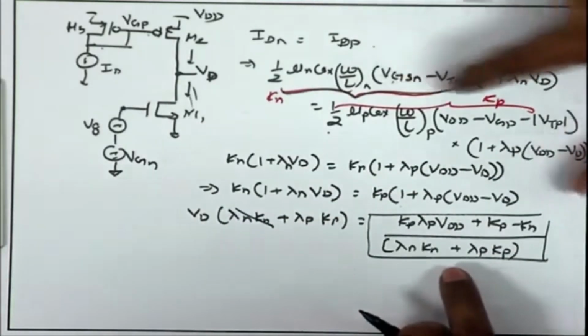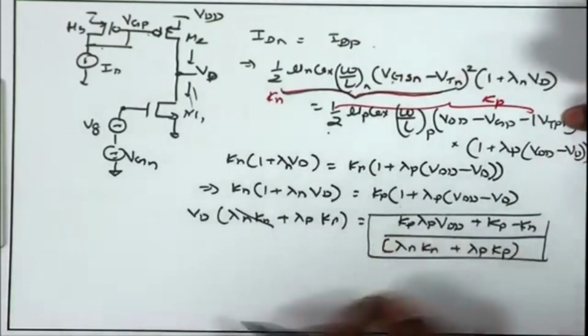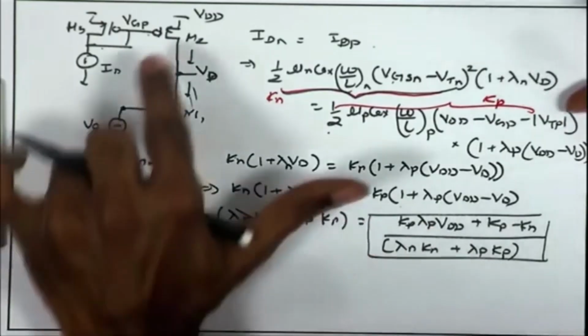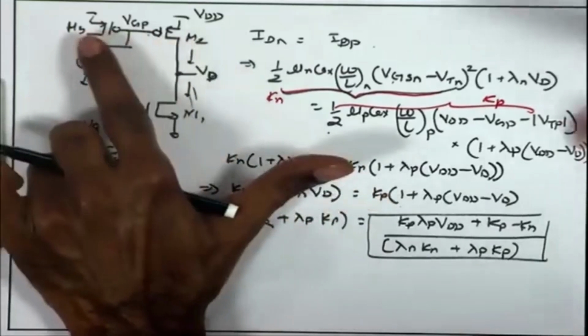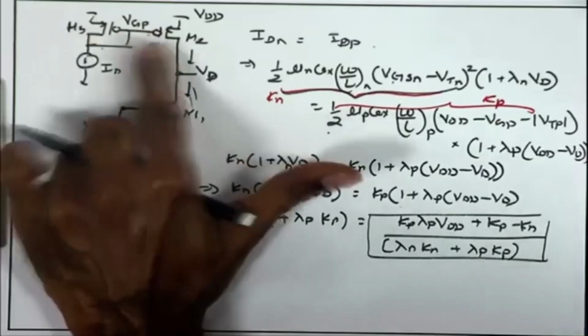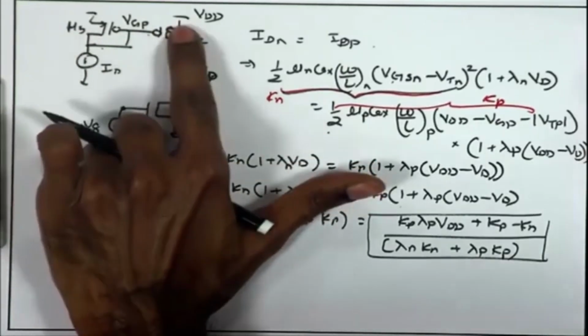So, here we have the terms Vtn, Vtp, which can vary. The threshold voltages of NMOS and PMOS are not very well defined, and their ratios can vary. As we said, for 2 PMOS or 2 NMOS, we can ensure good matching between the Vt of 2 PMOS or 2 NMOS, but not between the Vt of 1 NMOS and 1 PMOS.